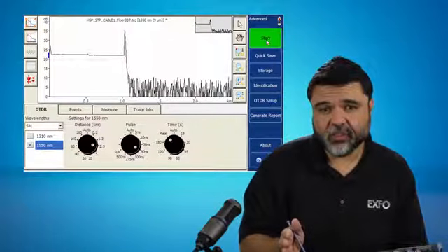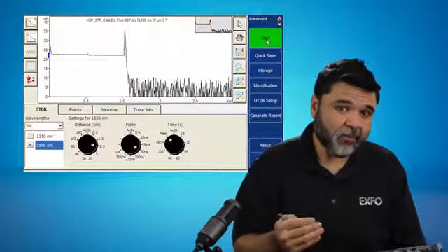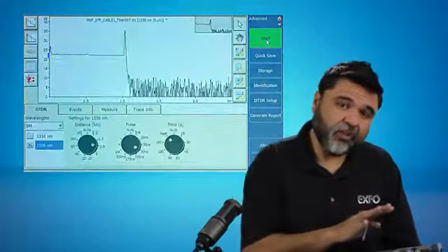You can cause an outage from too much power. And so keep that in mind when you see a pinch in the fiber. It's important to characterize your fiber before a system goes hot. But unfortunately, there's a lot of fiber in the ground today that has macro bend issues that have been there for 10, 15, 20 years, running short wavelength systems like 1310.